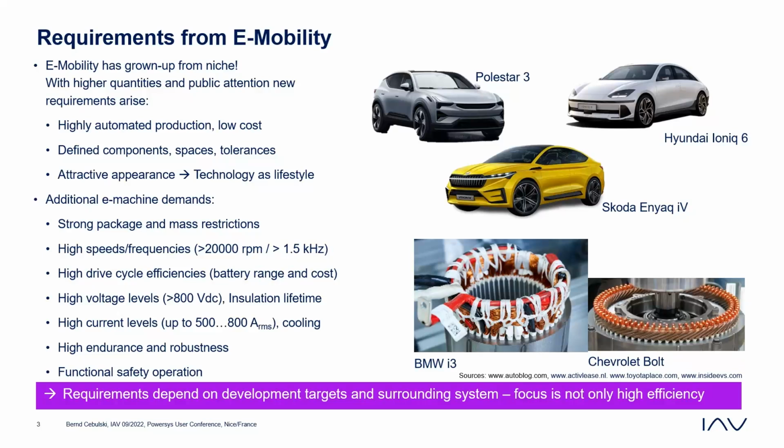The problem is that the driving cycle is always located in the lower part of the torque. That means a lot of things: auxiliary losses in the magnets, bearing losses, mechanical things like air dragging losses, especially with high speed, are very important. Not only the copper losses. So everything has to be looked at up here.